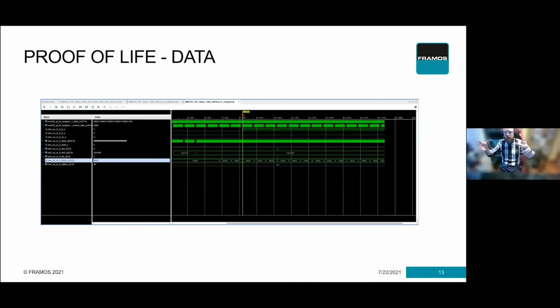What that means is the FPGA is normally waiting for a complex string of bits coming in at the beginning of every line to tell you it's a new line. And then you can say, right, at the end of these last two zeros, that's when my pixel starts. An error where your FPGA is not catching that, or you're not seeing it, can cause a problem. What is it? Is it the sensor not speaking correctly or not configured correctly, or is it the FPGA?